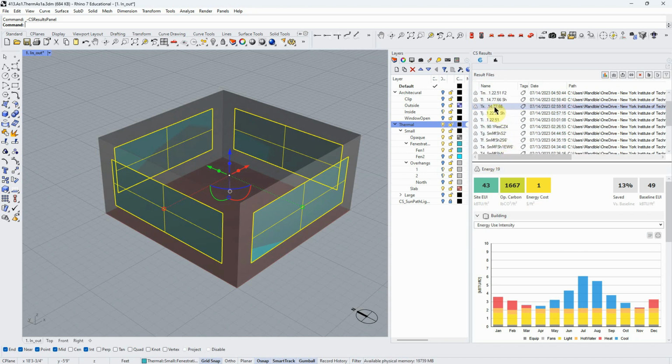So this is the new glazing. Let's just remind ourselves. We had the low solar heat gain coefficient glazing with this cooling load, and this is our heating load. We added shading. It actually got a little bit worse, but we got rid of the cooling load. I mean, our energy usage got a little bit worse. Now we tried a high solar heat gain, triple pane glass, and it actually got much worse. And if we add that same shading, I can basically get back to the same values I was at before with the unshaded low solar heat gain coefficient glass.